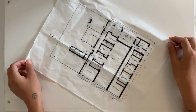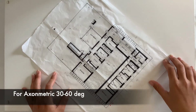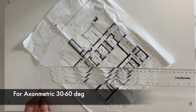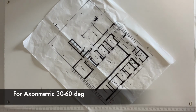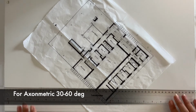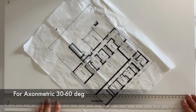So this is an example on how to set up your drawing, but you'll have it taped down. Before we tape it down, we have to make sure that the corner meets a straight line below. So you're grabbing your T-square, you just place it on the drawing board, lock it into the side to make sure that it's giving you a straight line.